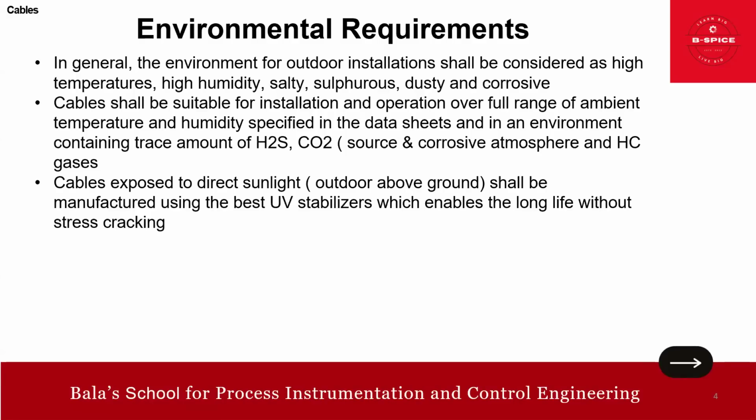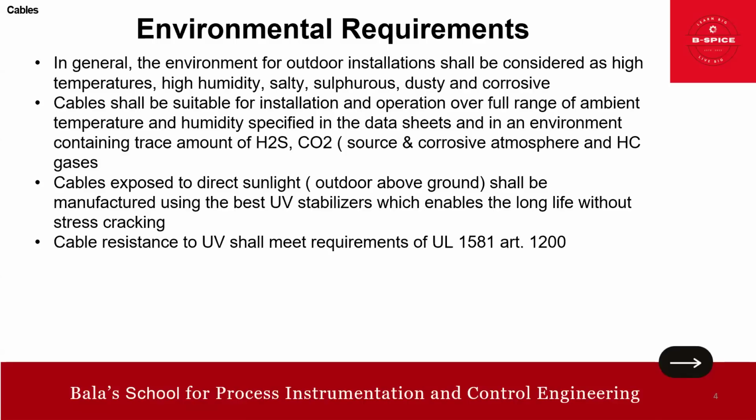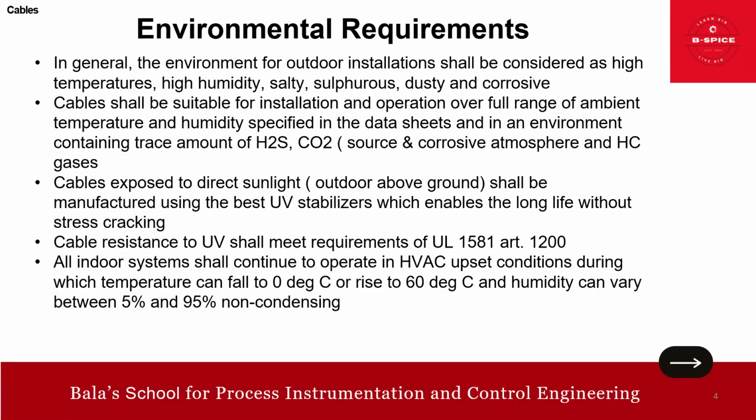So the point is, cables exposed to direct sunlight shall be manufactured using the best UV stabilizers. These are all from the environmental point of view. Cable resistance to UV shall meet the requirements of UL 1581 Article 1200. That is another piece of information.